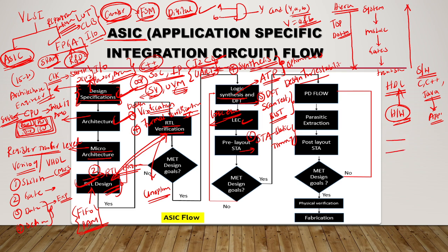studied the AND gate. So with the AND gate, you are getting the inputs A, B, and output Y equals what? A and B. This is the output you get at zero simulation time. But there will be some delay for the AND gate, that is propagation delay. So we'll study about delays, setup time, hold time, and violations, setup violations, hold violations, and these things. They will work on these under STA.